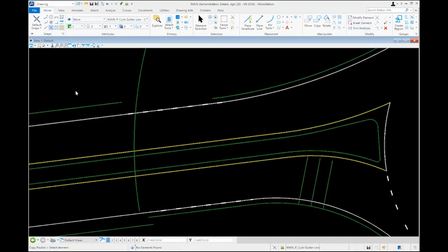And if we just do a quick double check, that should put us 20 feet back approximately from the edge of that raised splitter island. So we're within that 20 to 25 feet of the marked entrance line. So that's where we want to be. And what we'll do next is extend the center line up to approximately the middle of the splitter island. We want to try to get an angle point established as close to the center of this splitter island as we can get.